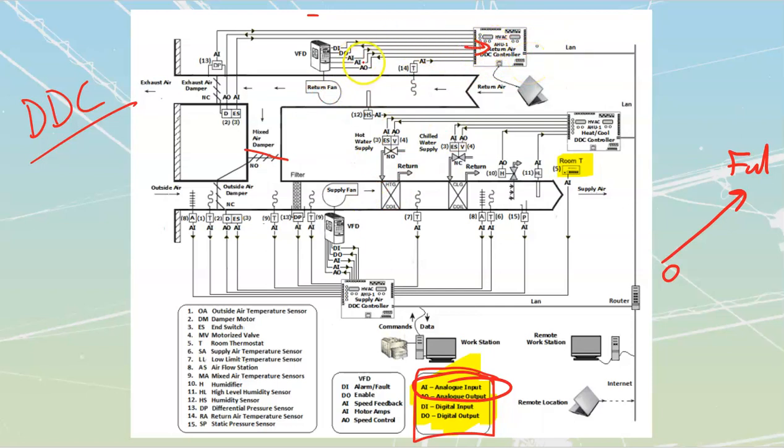I'm also going to, on another one of my analog inputs into the DDC, monitor my motor amps. Once again, just for protection's sake, that if for whatever reason I start to overload it, I can shut that thing down and protect that motor.